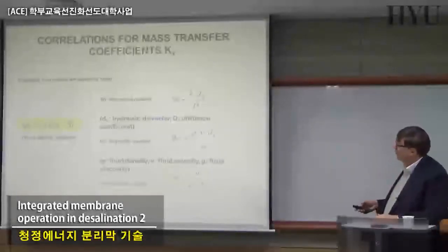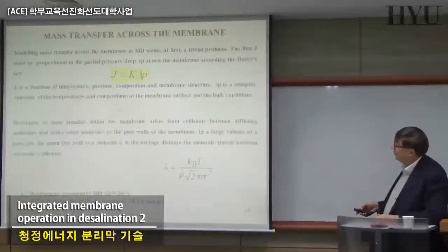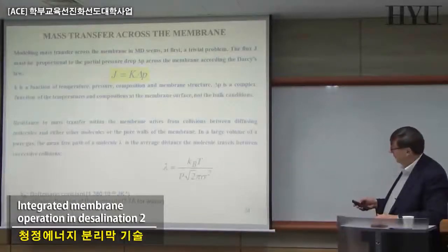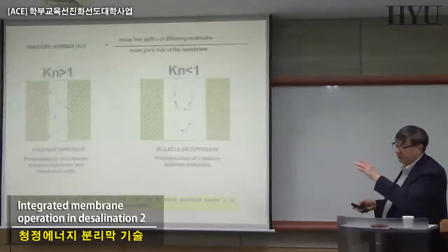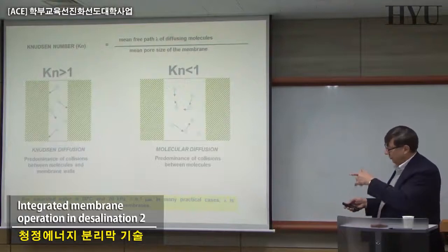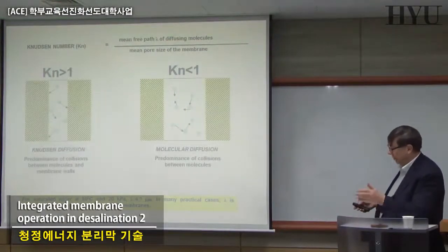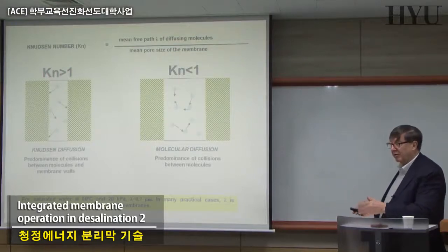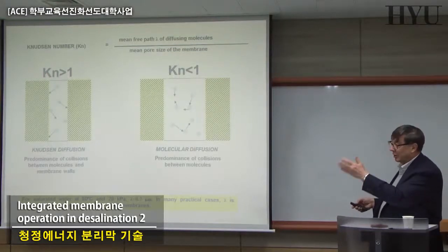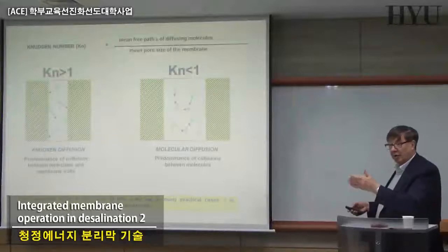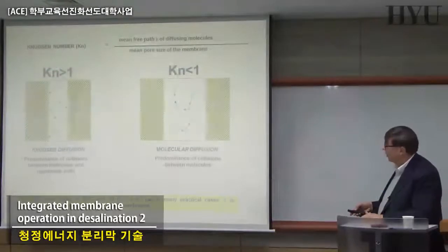What is becoming important, vice versa, is the transport in the membrane. Here we will discuss it in the spring, but you have the same kind of equation that you have been learning in gas separation, etc. Depending on the size of the pore, it can be Knudsen, it can be viscous flow, the Hagen-Poiseuille equation, so nothing really different.